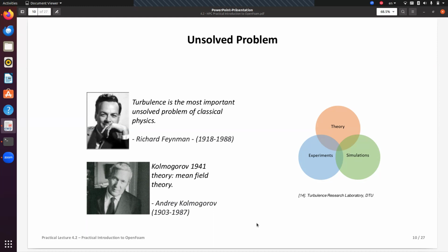The accuracy of LES is much better than RANS, but it's not an exact solution, and LES is much more expensive in computing than RANS. And the other one is direct numerical simulation, called DNS, which provides the exact solution, but it's so expensive and costly that usually for real problems they don't use it because it's costly on the computer.